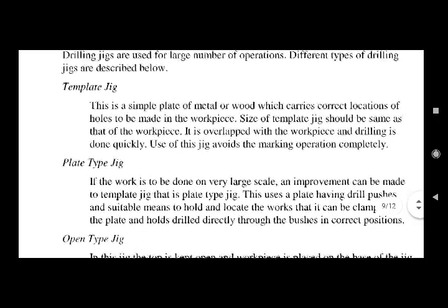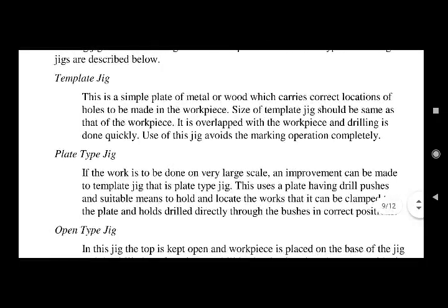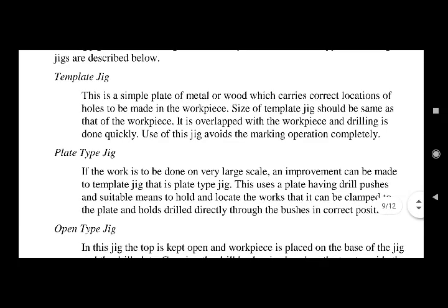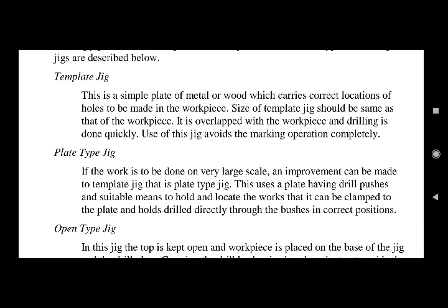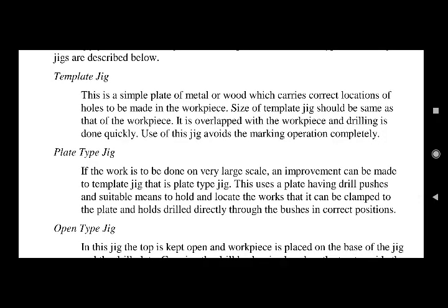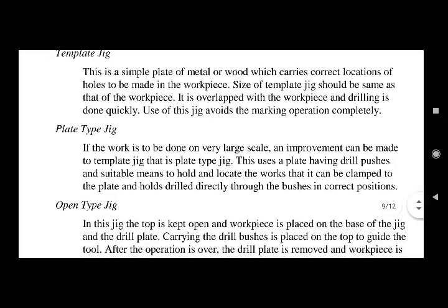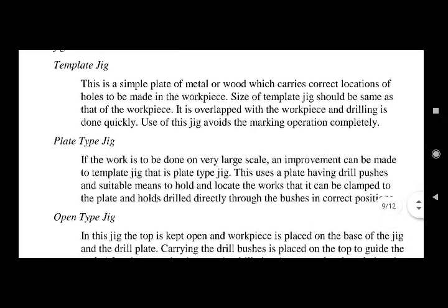This is a simple plate of metal or wood which carries the correct locations of the holes to be made in the workpiece. The size of the template jig should be the same as that of the workpiece. It overlaps with the workpiece and drilling is done quickly. Use of this jig avoids marking operations completely. That means it is very easy to handle a template jig.